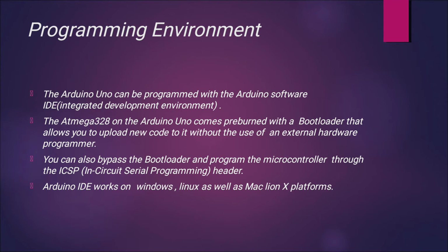Arduino coding or programming environment. The Arduino can be programmed with the Arduino software, that is the IDE, Integrated Development Environment. The ATmega328 on the Arduino Uno comes pre-burned with a bootloader.